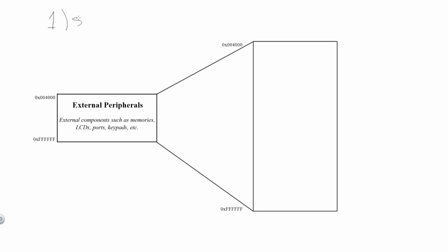The first thing is the size of the chip select. The second thing is called the base address of the chip select. The base address is just the first address in the range of addresses that is to be associated with each chip select. So the first thing that should be determined is the size. This is often determined by the type of device that is being added. There's a discrete set of possible configurable address sizes between 256 bytes and 16 megabytes.